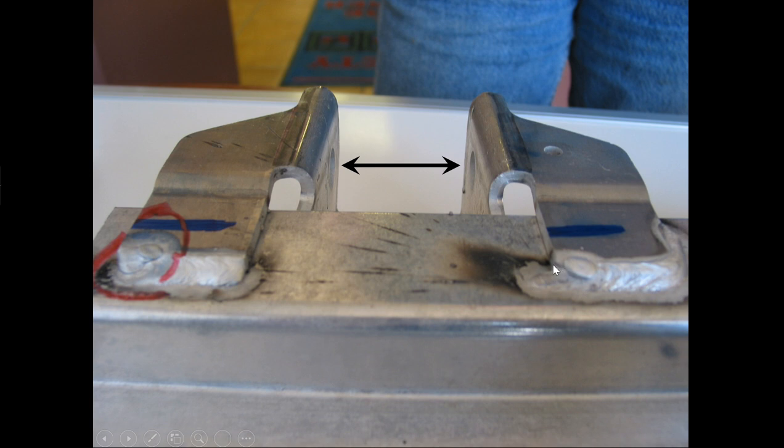This is where your TIG welding skills can come into play. You can do things with the TIG welder that you can't with the MIG welder when it comes to doing reprocess work. There's a lot of companies that say, I want to do MIG welding for my reprocess work. Well, congratulations, but you're not fixing anything. It'll just lay on top. Because now there's a weld in place, we need more than just heat.